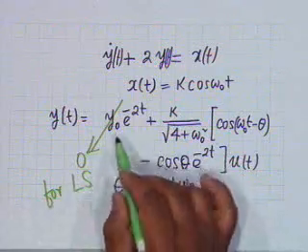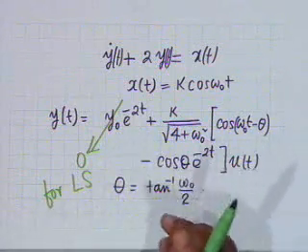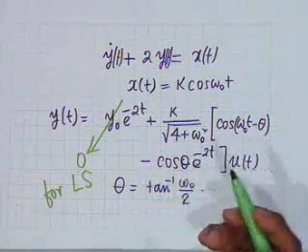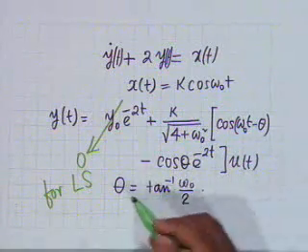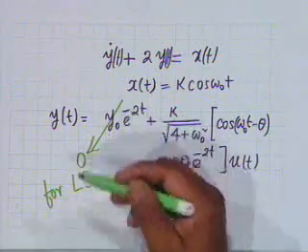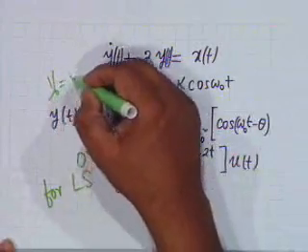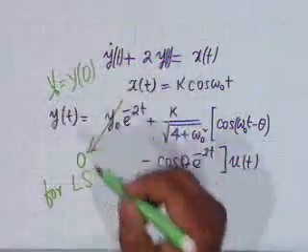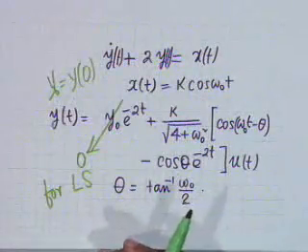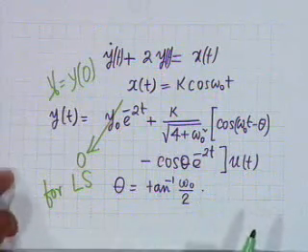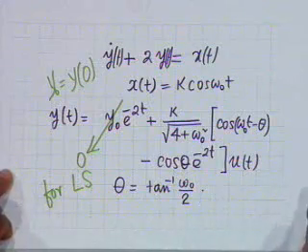The only thing we are left with is y0 e to the minus 2t, and it should not have an existence when the input is equal to 0 if the system has to be linear. Now this means that the initial condition y0, you recall, y0 was equal to y of 0, must be 0. That is, the system, although a dynamic system, must be relaxed at t equal to 0. It must not have any storage of values.